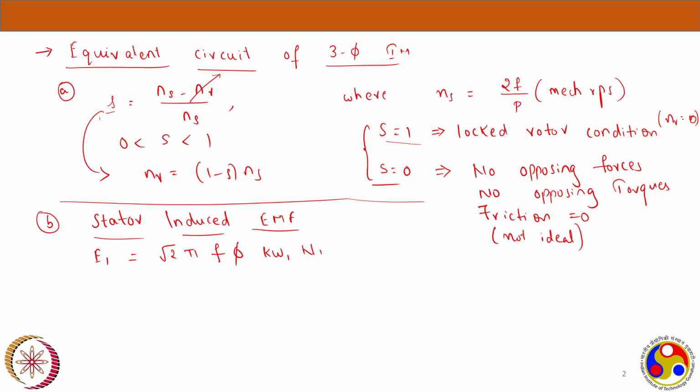Now when we multiply this winding factor Kw with N1, the turns in the stator side, it gives the effective turns that will be useful in producing the flux, because of the pitching and the distribution, you might not be utilizing all the coils effectively. So the voltage produced will be less than the full maximum voltage that could be possible. We had discussed that two weeks before. So if you multiply this Kw with N, that will be the effective turns.